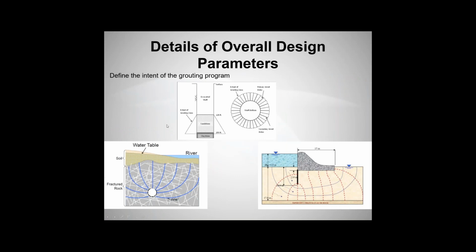The next step is that we really need to look at the intent of the grouting program. While a lot of similarities exist between, say, a tunnel, a shaft, or a dam foundation, there's a lot of nuances between each program. Principles associated with dam foundation grouting may have some similarities with tunnels, but they're different. You're working under different conditions. And so, really, are we just trying to limit groundwater infiltration into the shaft?